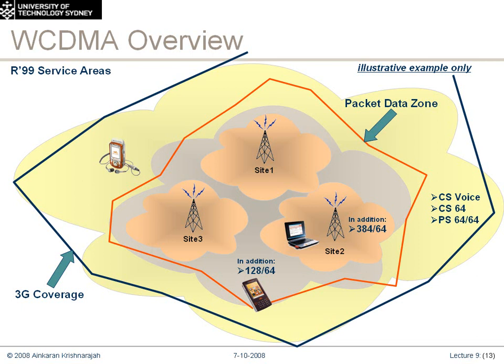The radio network planner here in this particular case has provided speeds of packet 64 throughout the entire network, which are in yellow. Together with that is CS voice, or circuit switch voice, which is our standard speech service. But as we move inwards towards the core part of the network where the 3 base stations are, we can only support 128 in the downlink, 64 in the uplink, and then even closer to the base stations, we see some spotty coverage of 384.